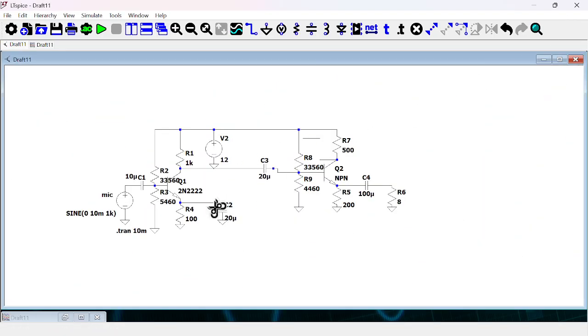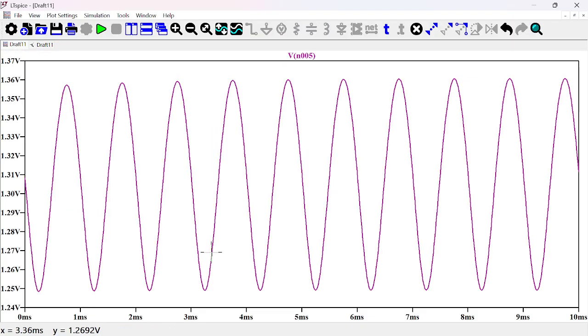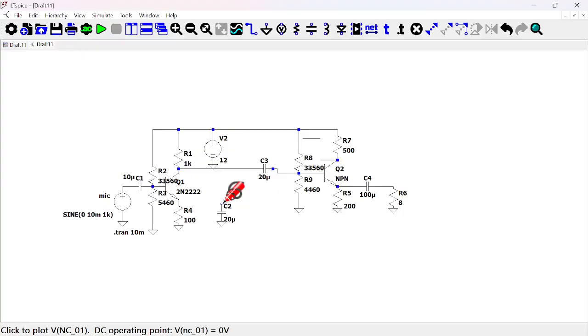So I think this guy should do the trick. And that is it, we solved it. So after a bit of troubleshooting, what I noticed is that guy was the one causing the issue. In being greedy, connecting this bypass capacitor meant I was getting huge gains here, and that means that the signal coming in would move the VBE way above 800 and way below that when it adds up.